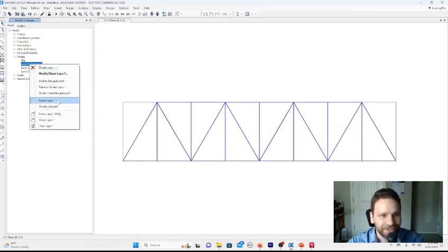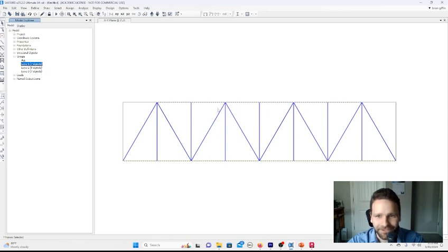And if we go to select layer 1, for example, we can basically select all the structural members from our AutoCAD file. So another thing to note is that even if you drew your structural members such that there wasn't necessarily a joint connecting endpoints of a given member, new joints will be inserted at basically the connections or intersection points between lines in your AutoCAD model and the supposed structural members in your resulting SAP model. So there's a one-to-one correspondence most of the time between points you've defined in your AutoCAD file and joints in your structural SAP2000 model, as well as lines in your AutoCAD file to structural members or elements within SAP2000.